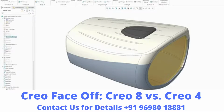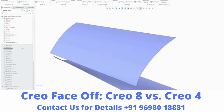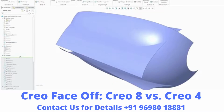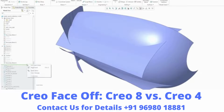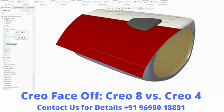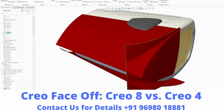Often when performing complex surface modeling, you want to visualize the shape of surfaces and quilts the way they looked in the past history of your model prior to modification or consumption. In earlier versions, this often meant rolling back the model to a previous feature in the model tree. Now in Creo 8, this can be accomplished using Show Snapshot. This provides quick insight into the design intent of the model.